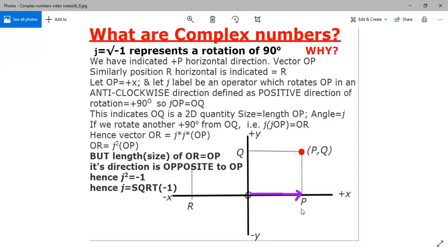So we will explain. If we have a particular coordinate pair PQ, if we mark along the P dimension in the horizontal, and draw a line back to the origin, we have effectively a unit vector, whose length explains what its size is. And the angle with respect to a reference, which is normally the horizontal, gives its phase shift.